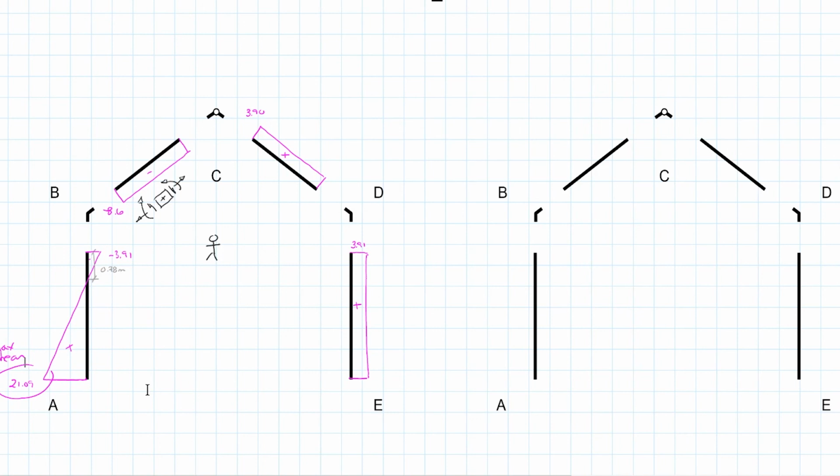We know it has a positive value of 42.95 at B, so I can draw those in. And we can see that we're going to be having a positive slope moving up from A, and it's going to reach a point of inflection and maximum at 0.78 meters down from B, so at about there. So if I were to draw this in, it would do something like that.